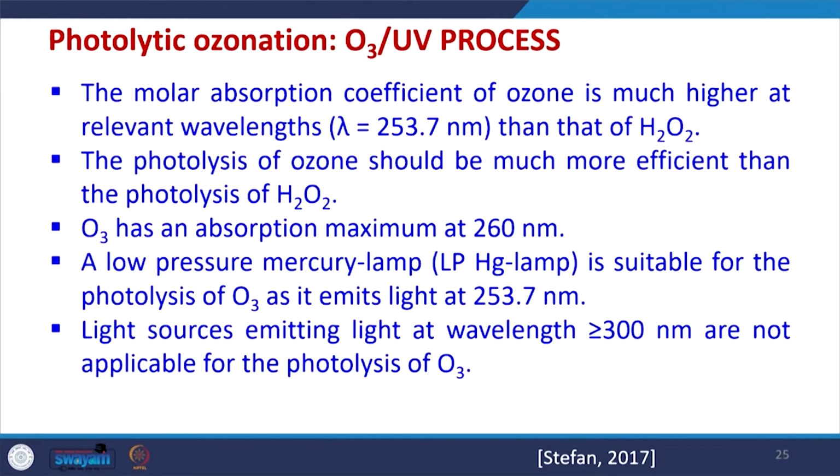Now, photocatalytic ozonation is also possible. We are not using any hydrogen peroxide. Here the treatment is done without hydrogen peroxide, but in the presence of ultraviolet light. The molar absorption coefficient of ozone is much higher in the relevant UV wavelength range.